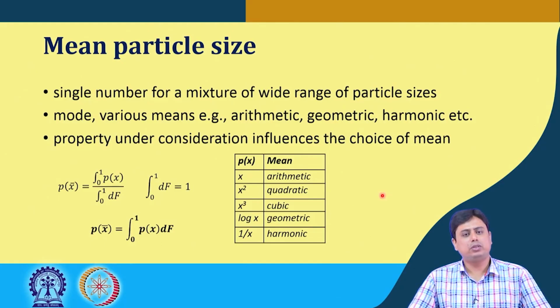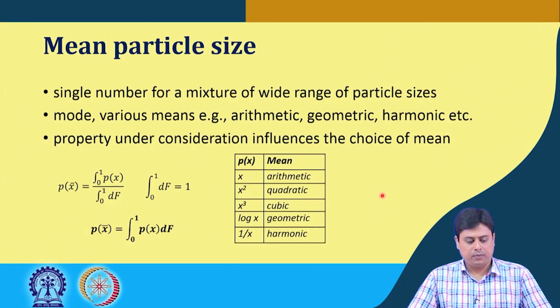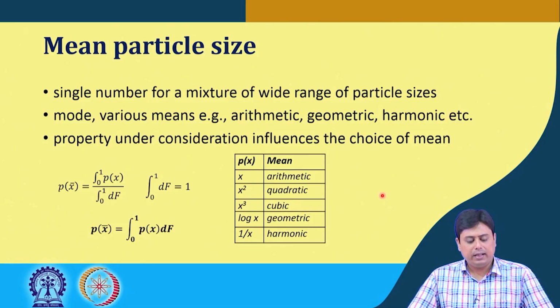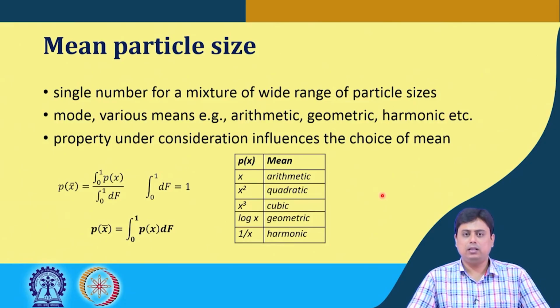Then you can apply the Kozeny-Carman equation or the Ergun equation for such applications, and there you have to put an equivalent d, or diameter. So, what would be that equivalent d? What is your consideration? We will see that slowly. Before that, let me tell you the different types of means that are statistically, or most popularly, used in such determination.